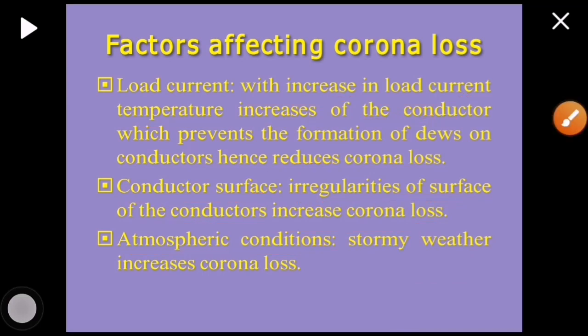And one more parameter is definitely the system voltage itself. The larger the system voltage, the more will be the corona loss. That is quite natural. But there is a limitation of going for larger and larger voltages from the transmission line design point of view.